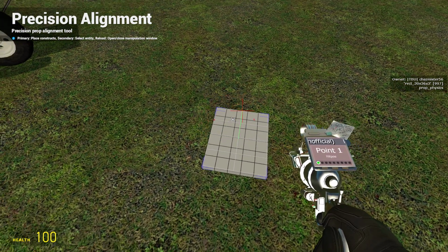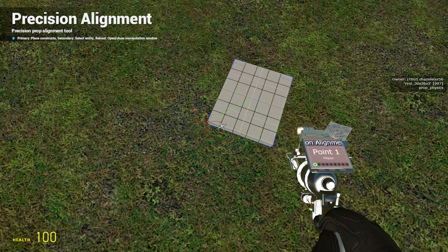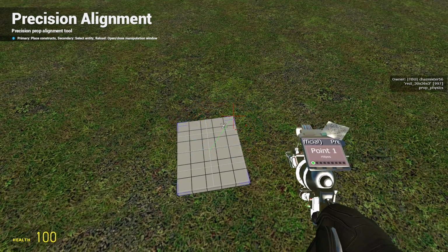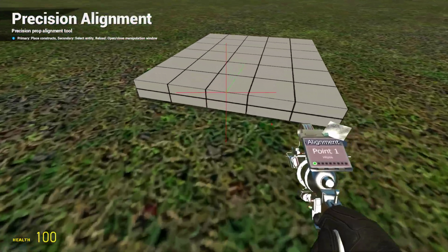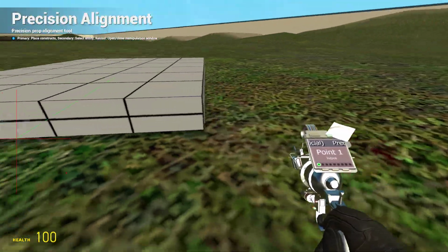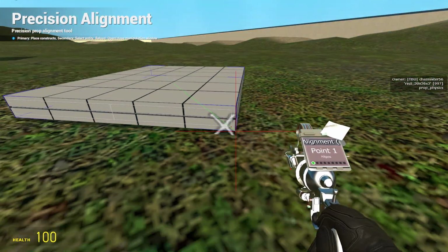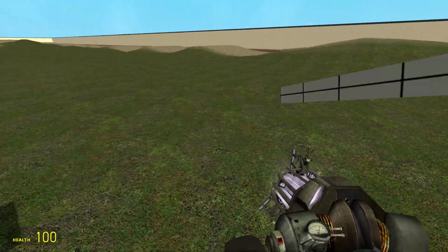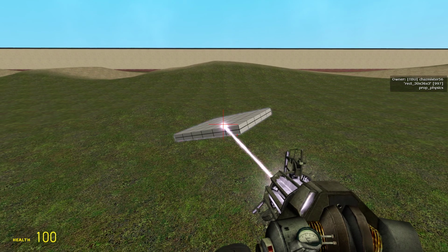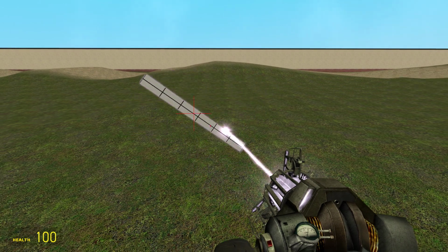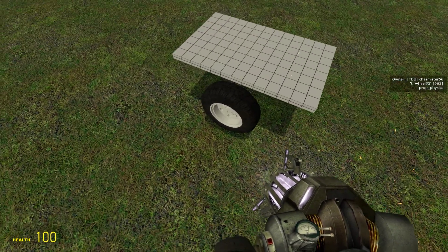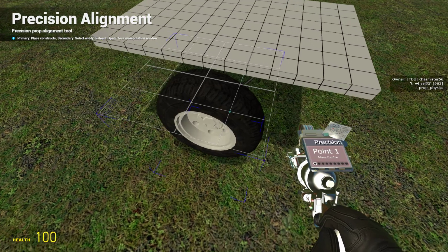Hit pause snaps to corners or the centers of a prop, and that can be changed by undoing these settings. But trust me, you don't want to do this. This is very helpful, having it lock around on the edges of the prop. You can also do it here, middle, down on the bottom, on the corners. And then if you want to go mass center, which is kind of obvious, it sets it in the very utmost center of the prop, right in the middle. So now with that in mind, when you make spherical wheels, you can't really set specific points with hit pause. You can mass center them though.